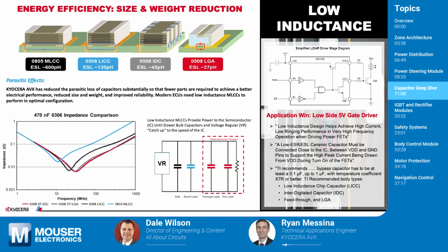A lot of times, if you need to power a transistor or something and you need stable, fast power right away, before your bulk caps can catch up and supply a more sustained power, this is where these low inductance MLCCs really come in handy, because they can supply power very, very quickly, whether you're opening a gate or activating a transistor. It'll allow that to have stable power super fast until your more bulk capacitance power areas are able to keep up and maintain that. But they're really, really great.